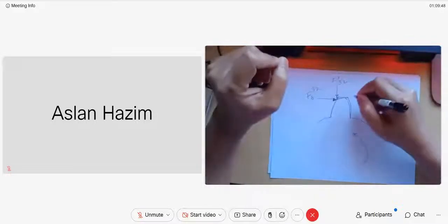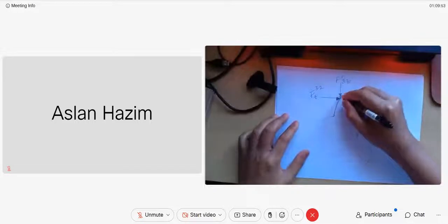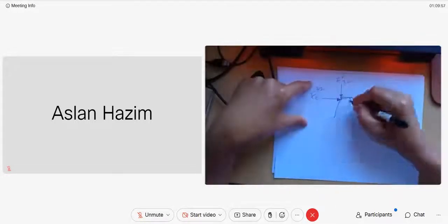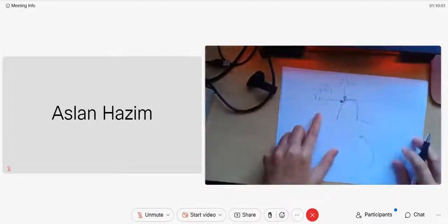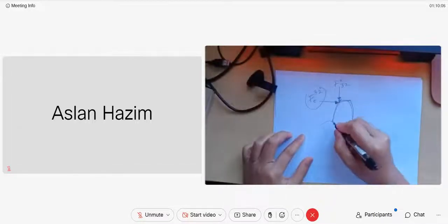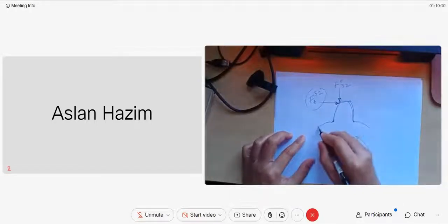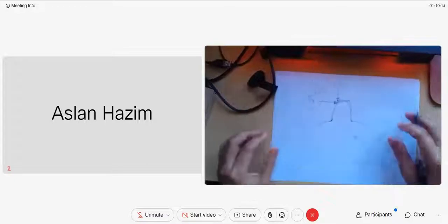Will this tooth survive or not? Can it sustain the load? If you look carefully, the radial load actually does not cause any effect and does not harm the gear tooth. The one that harms the gear tooth is this F tangent. It is critical, because this F tangent will produce bending stress, because here we have the bottom, the dedendum. So this F tangent will cause bending stress.